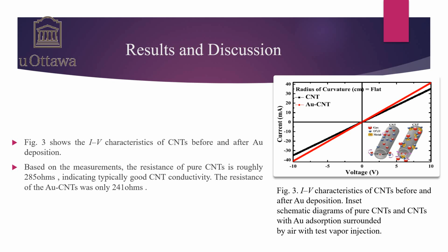The inset in figure 3, which is the pure CNTs surrounded by air, shows that oxygen molecules adsorb on the multi-walled CNT surfaces to generate chemisorbed oxygen species by capturing electrons from the conduction band.